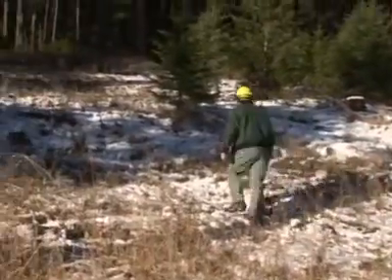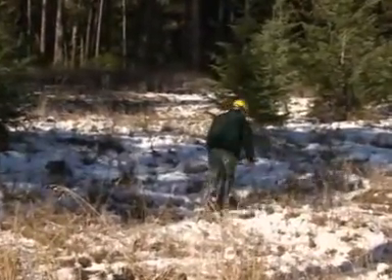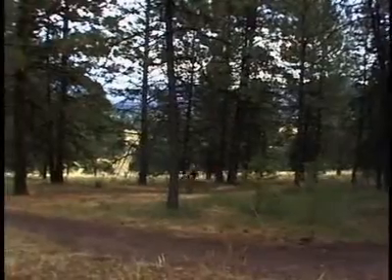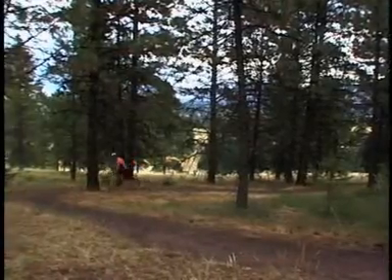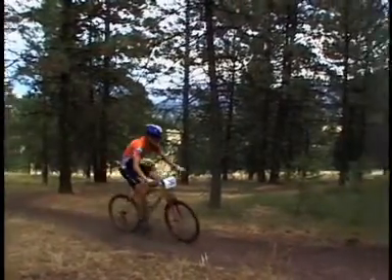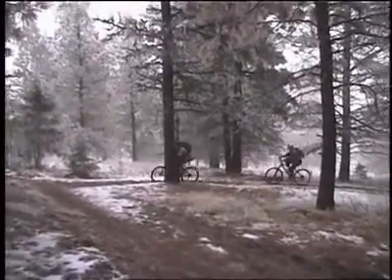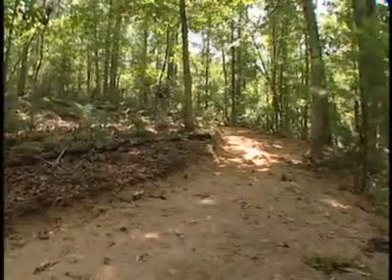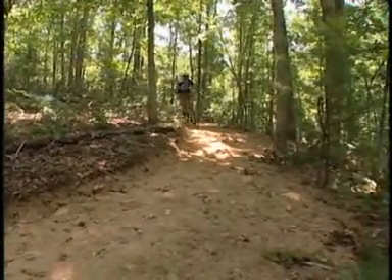By scouting out less aggressive slopes, like 7%, you can use climbing turns instead of switchbacks. Climbing turns are wider curves on gentle hillsides. They are easier to build, more sustainable, and give bikes a wider radius to negotiate a smooth, controlled turn. The radius of the climbing turn needs to be about 20 feet, about 4 bike lengths.